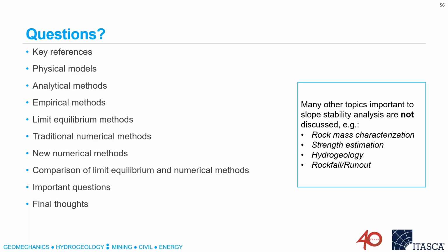If you use the Hoek-Brown approach of D, where the friction angle is reduced, then you end up with deeper failure surfaces that don't necessarily agree with reality. And so one of the things you should do, I think, in any analysis, and particularly when you're looking at shear strength reduction or factors of safety, is look at what the potential failure surface is.